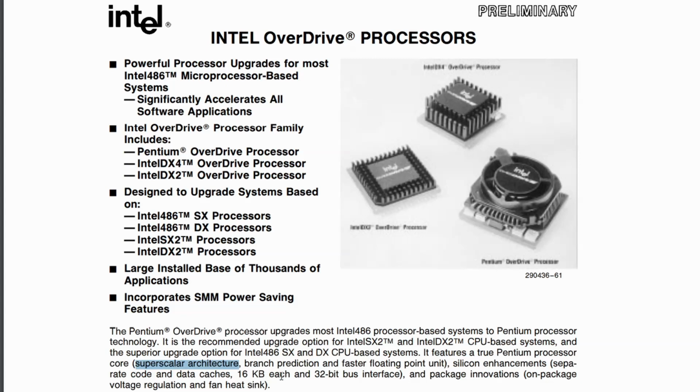86. Then the second very important improvement was a faster floating point unit, and this actually gave an edge to the Pentium CPU as more and more games back then switched to floating point operations. Then there are a few changes with the organization of the cache memories, but then okay, the last very important difference is that the Pentium CPUs typically use a 64-bit data bus that basically doubles the bus throughput. So in the end the Pentium processor has doubled the processing speed, doubled the data throughput, and a better floating